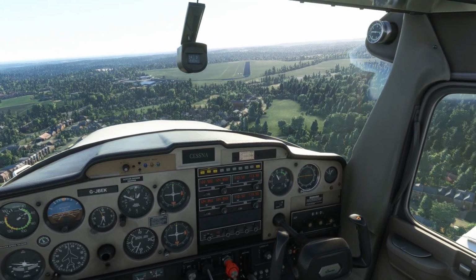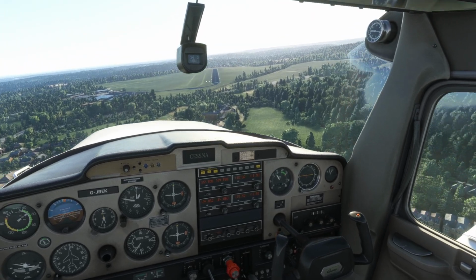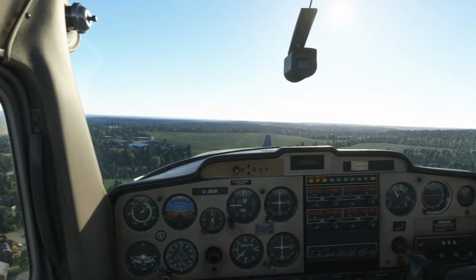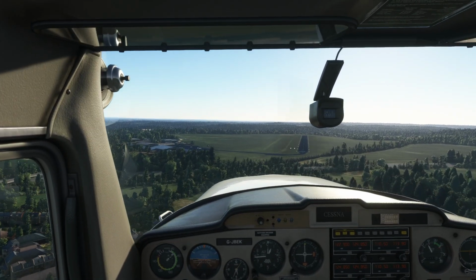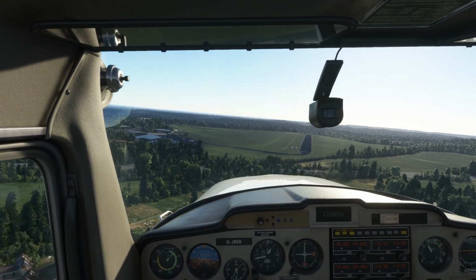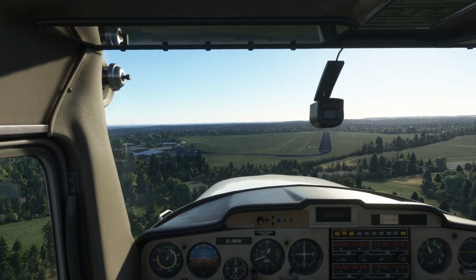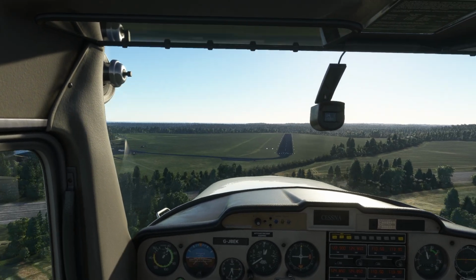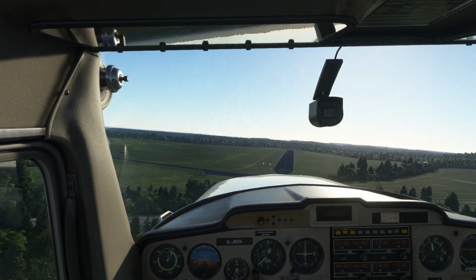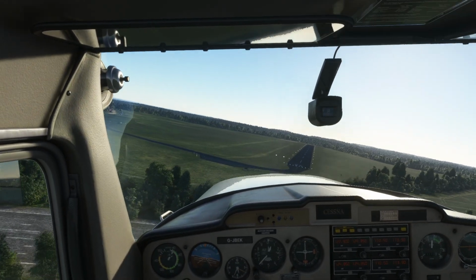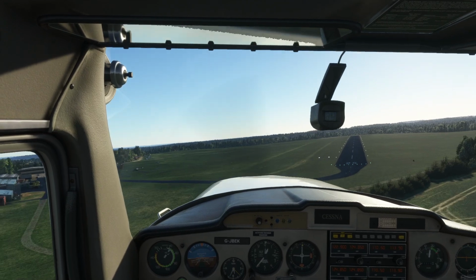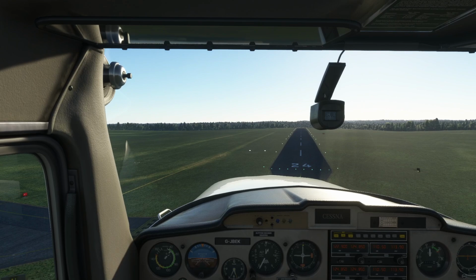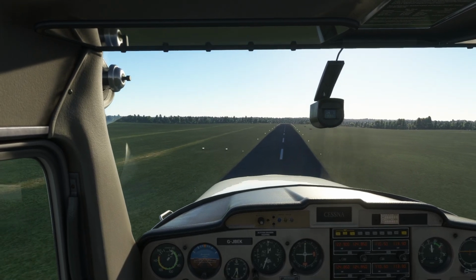You know what, I think I might rather be high, seeing as how turbulent this was when we were on the VASI lights. So we're crabbing. Let's center the view up and sit us up in the cockpit. So we're crabbing about 10 degrees. So the crabbing technique is you get over the runway. Whoa, that turbulence really is wicked. We're going a bit slow, that's why. I guess it's the main road causes some of it. So having a bit more altitude didn't really help us.